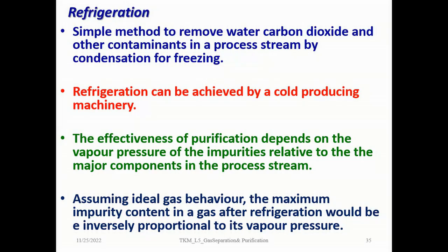As you have seen, the boiling points of these are very far apart, because of which the vapor pressure of helium over the nitrogen will be large, and therefore it is separated as vapor, whereas the vapor pressure of the nitrogen in the liquid state will be smaller, so it will get separated very well. So nitrogen and helium get separated very well because of the process. A gas mixture gets separated very well when the boiling points are well separated.